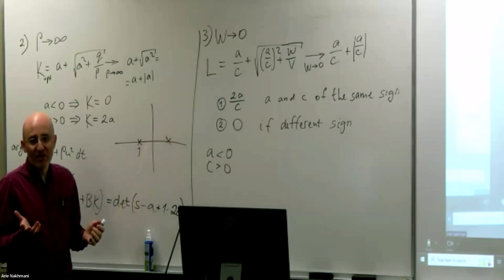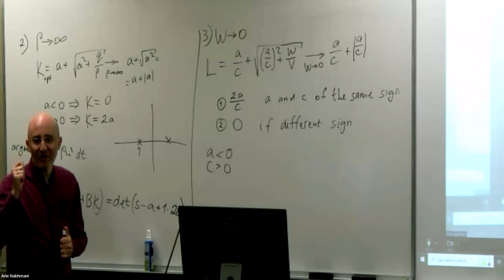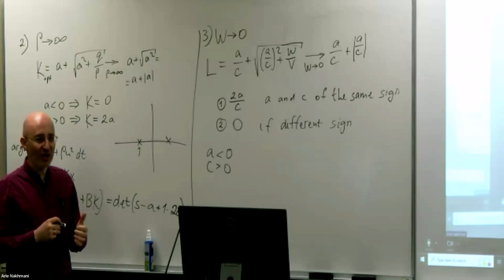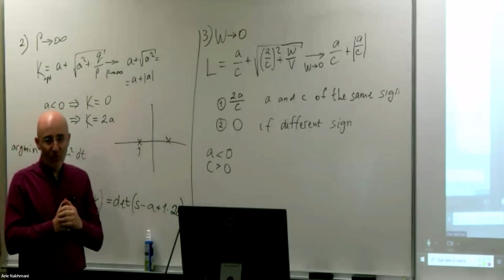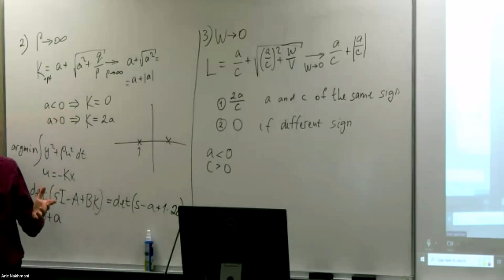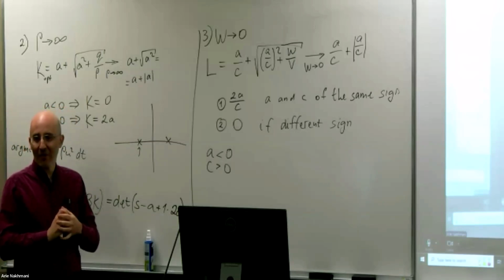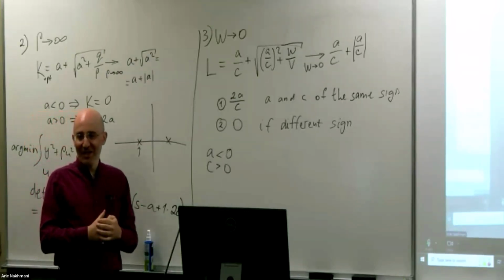Kalman gain 0 means your error from your measurement is just your measurement noise, because your system is precise, exact. Your system is producing exact values for your development. Okay, you believe it 100%. Completely ignore the output. You don't care about measurements. Measurements are noisy. So when W goes to 0, you say, practically speaking, that your model is perfect. You don't need any measurements. You know where the x's are, just based on the model. Which is obviously not realistic, but this is the assumption here.